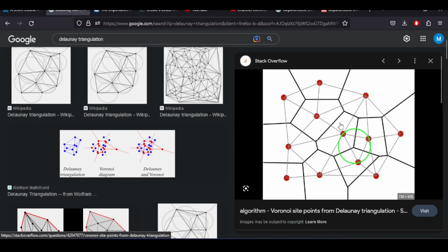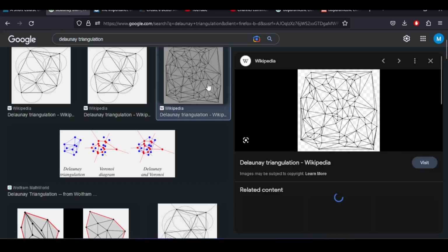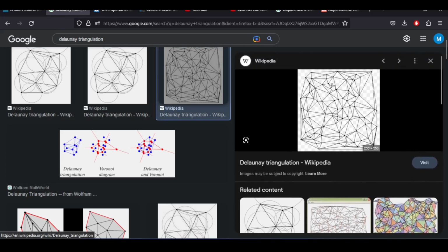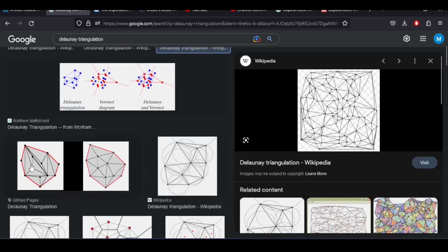This is a lot of details I will be talking about in my deep dive. For now, I'll just leave it as is. Of course, this triangulation now here is an abomination. You can modify it and improve it by adding constraints to this triangulation. For example, one constraint is to constrain the minimum angle. The angle should be, for example, more than 30 degrees. Well, this is maybe a talk for later. I mean, take a look. This is an abomination, and this is actually better. The same points are used in a bad Delaunay triangulation, which has absolutely an abomination of elements, and a good Delaunay triangulation, which is a constraint Delaunay triangulation.